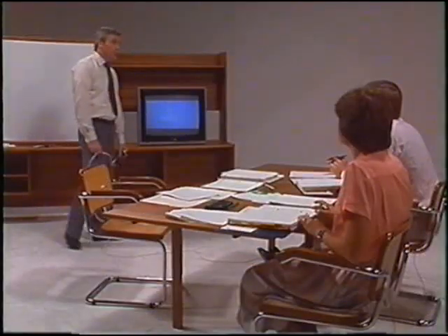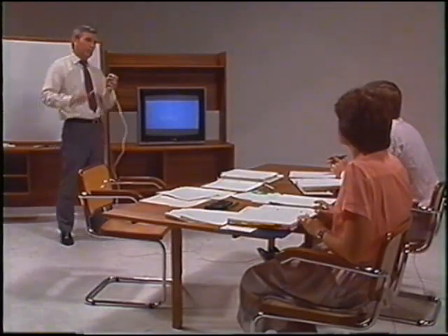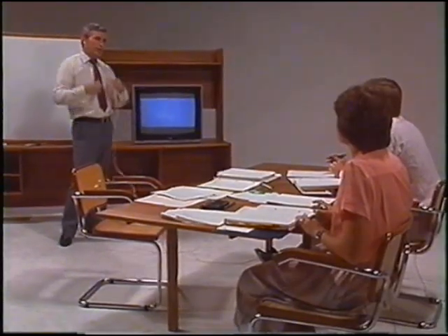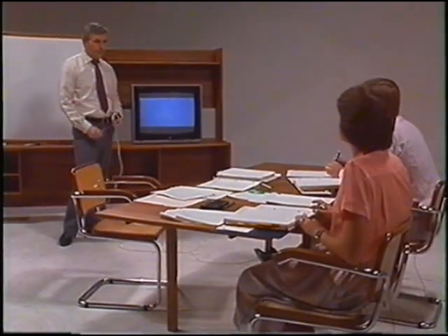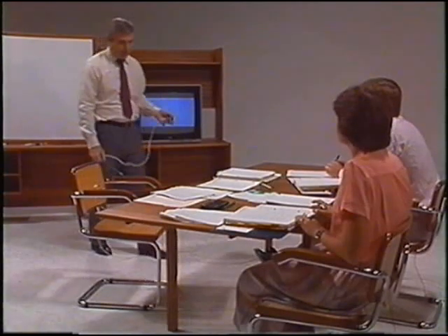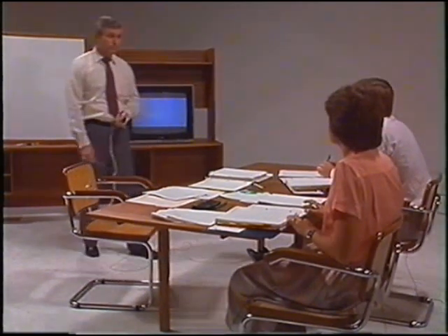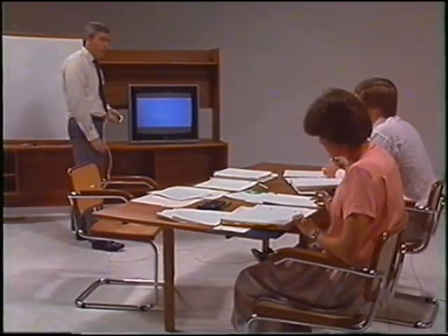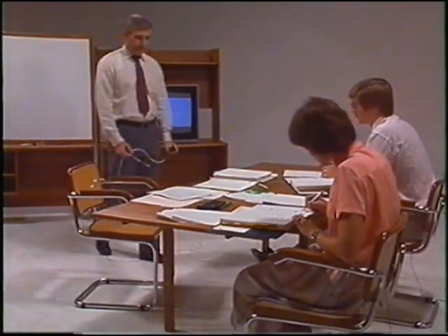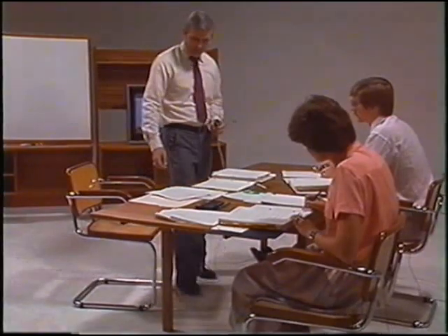Also, that critical wavelength that was calculated, is that in all directions from the front, or is this a two-dimensional phenomenon? Actually, it's a three-dimensional analysis, but the critical wavelength is the dimension lateral to the propagation. Okay? And a more proper way to say it is that the critical wavelength must be smaller than the minimum lateral dimension in order for fingers to propagate. Okay, so much for viscous fingering.